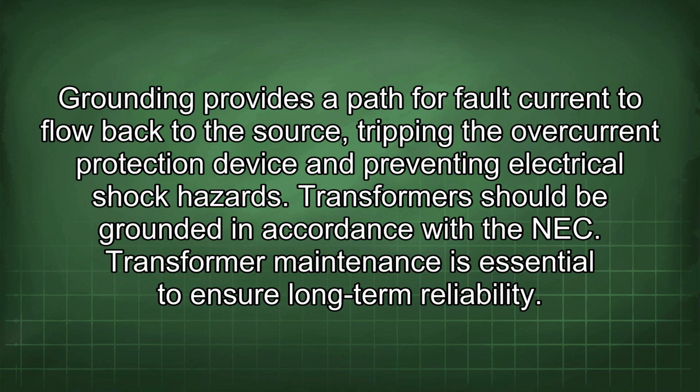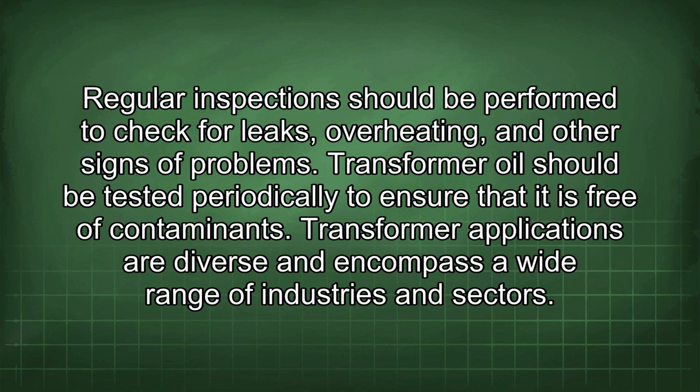Transformer maintenance is essential to ensure long-term reliability. Regular inspection should be performed to check for leaks, overheating, and other signs of problems. Transformer oil should be tested periodically to ensure that it is free of contaminants.